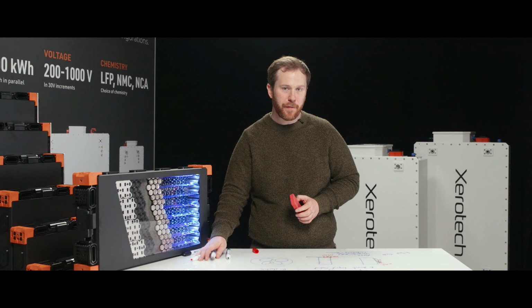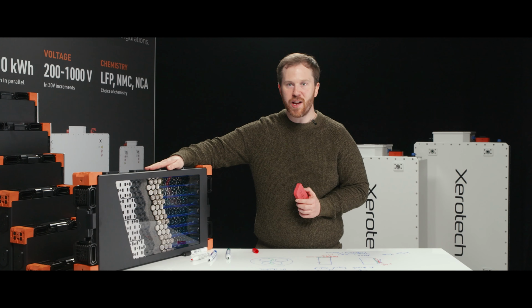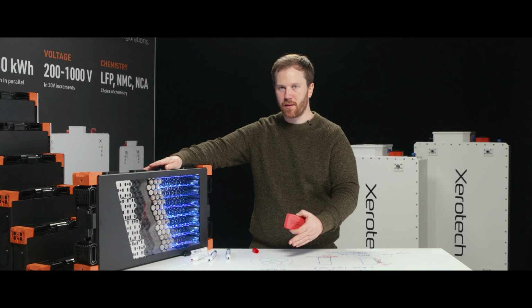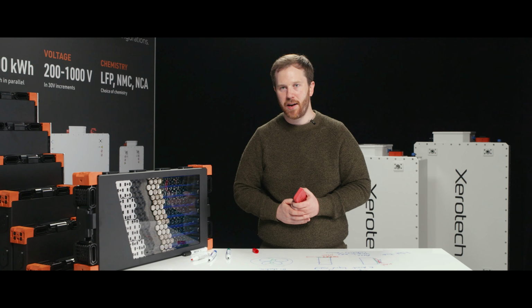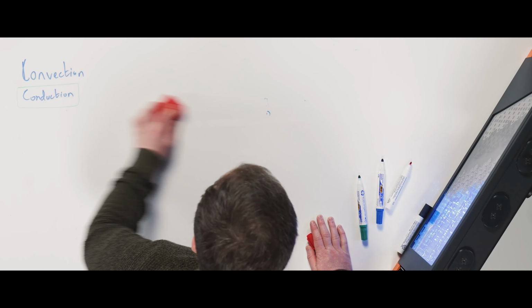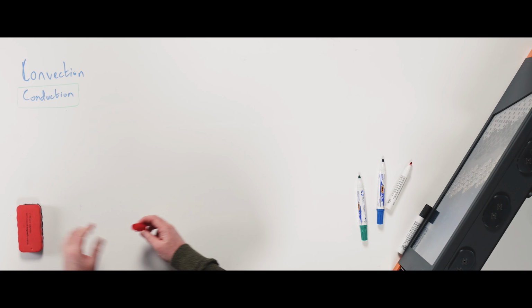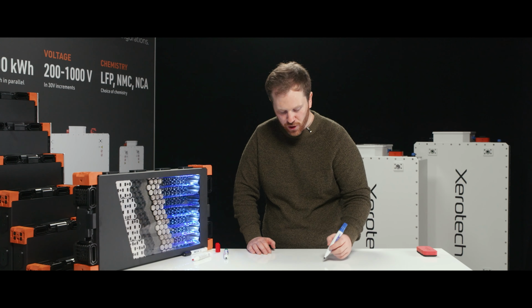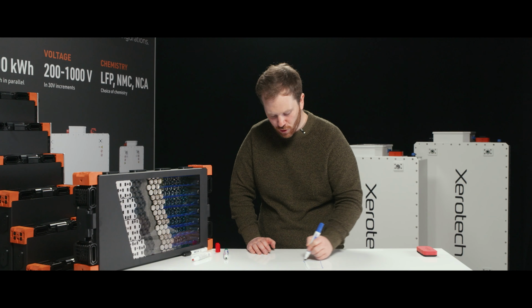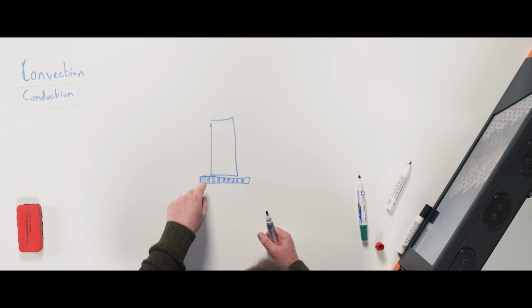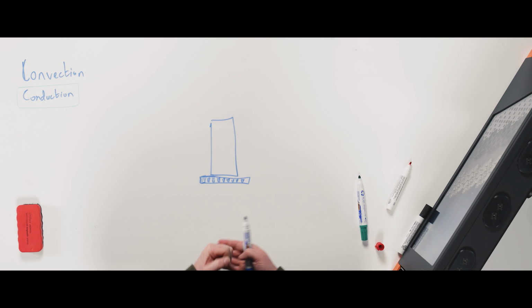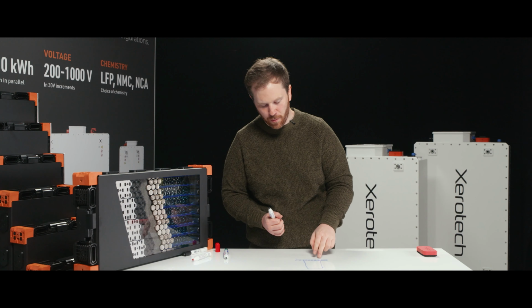So we're going to go into some specific details now of the considerations of real battery pack engineering, and actual practical stuff, now that we have a little bit of an understanding of the laws of physics here. One of the other factors you have to worry about when designing your battery pack is actually flowing the water through that heat exchanger. The vast majority of them are extruded aluminium heat exchangers, meaning that there are little holes in here that they're pumping water through. And another law of physics to do with pumps is that you need a force, you need pressure, to pump water through something.